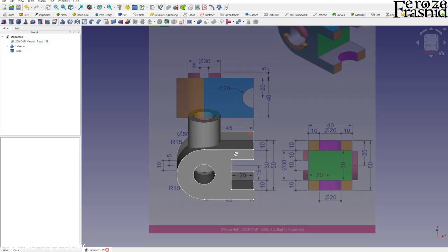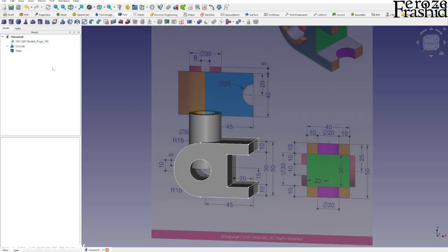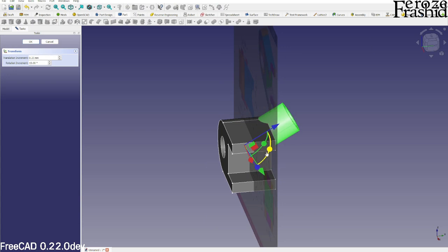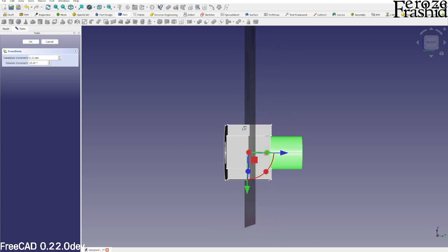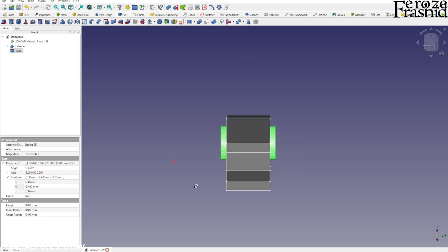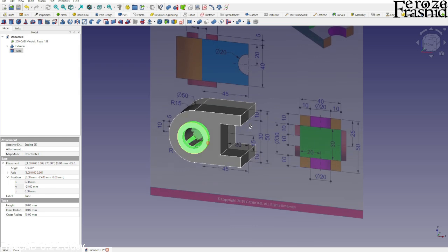Hit OK. As you'll notice, it's in the wrong place, in the wrong orientation. So let's go ahead, take care of that orientation. I want to make it flat. That's flat. Having 15 degree on the rotation increment on the angle helps. Sometimes I change it back to like 5 or 1, but 15 always helps. All right, and then I want to bring it backward on y-axis. On the y, I want to bring it backward by 25. Yep. So that's like halfway, height halfway up.